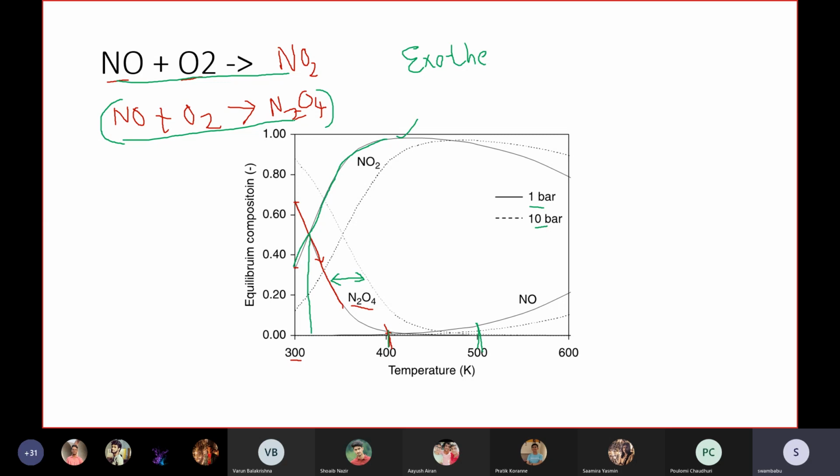Once you know the kinetics and thermodynamic equilibrium, we can pretty much tell that this reactor has to be operated at this condition. Why we operate at this pressure and temperature depends entirely on the thermodynamic equilibrium conditions, and how fast or slow we can achieve it is based on the kinetics. These are very important concepts.